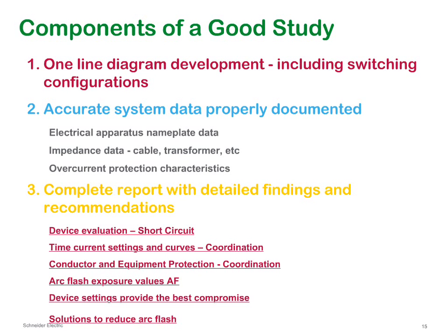And you have to make sure these are specification items. If you don't specify a short circuit study to be performed, it doesn't automatically get done. It's something that needs to be specifically stated that you want this. And the short circuit study is different from an arc flash study, because in a short circuit study we evaluate whether the equipment is rated properly for the short circuit currents. That's different from calculating the incident energy level, the amount of radiant energy that would be generated from an arcing fault, which is an arc flash study.